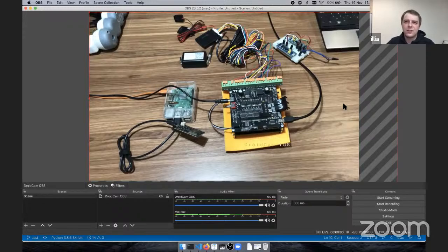They have similar or the same serial interface, serial number, so you cannot differentiate between them only by the serial number. And the USB enumeration mechanism, when you connect those things to the Raspberry, doesn't guarantee that you will receive the same adapters as the same dev TTY devices. So there is no guarantee this device connected to the Raspberry will always be TTY USB 0 or TTY S0. That's why we selected to go with a single Raspberry per device rather than connecting a lot of even homogeneous devices to the Raspberry.